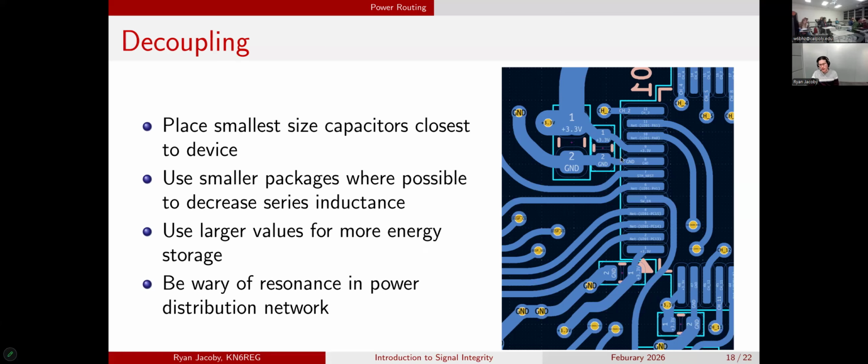But there's decoupling capacitors. The power comes in at the top here. One of them is this really big thick trace here. We have one capacitor here, next smaller capacitor nearer to the part, and then the power input to the part here. This is an STM32 microprocessor here, and then I pulled the ground plane or the ground trace out, and then I could only fit one via here. There's other things on layers behind here that prevented me. It would have been nice to put a bunch of vias here and put it closer to these capacitors.